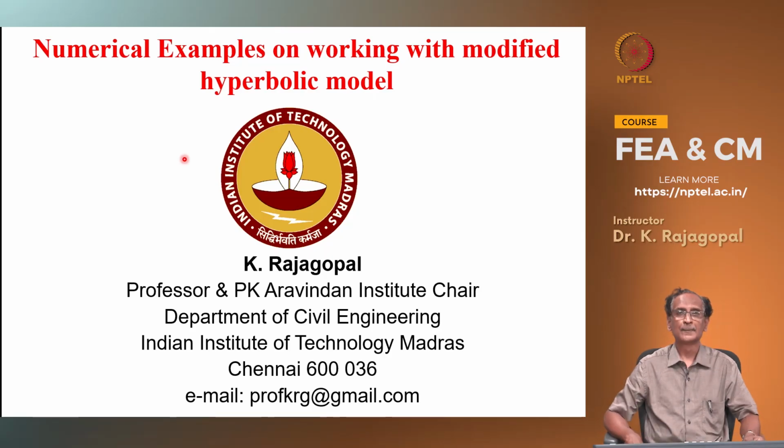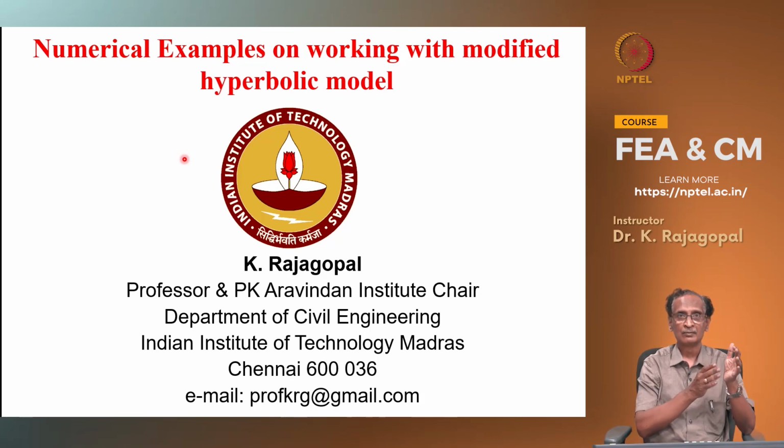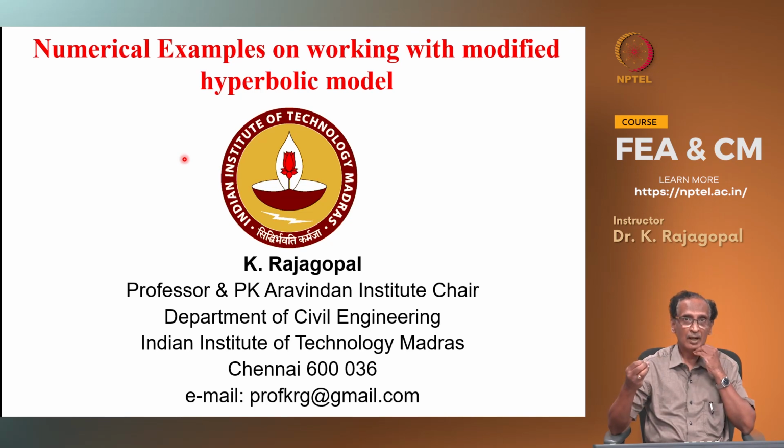So, hello students, let us continue our discussion on the modified hyperbolic model. In the previous classes, we had seen some theory behind the modified hyperbolic model, which was formulated in terms of tangent Young's modulus and then the bulk modulus. And I have also shown you one Excel spreadsheet program. And in today's class, let us do step by step calculations and then also try to implement our stress correction procedure that we had learnt in the previous class.